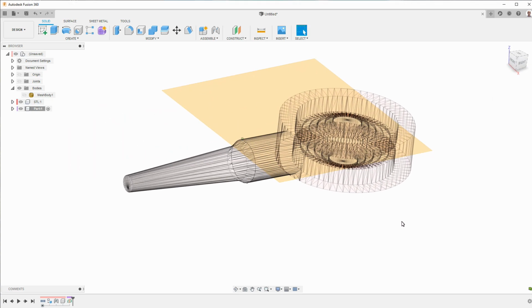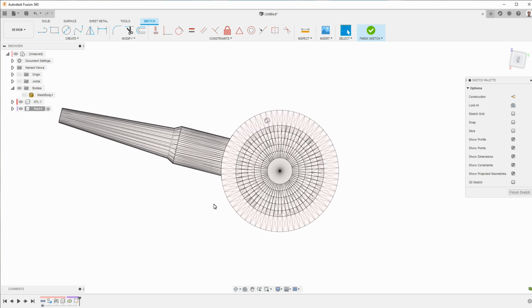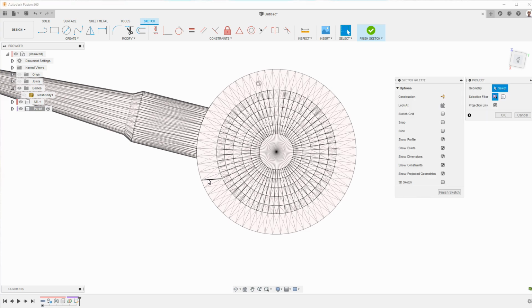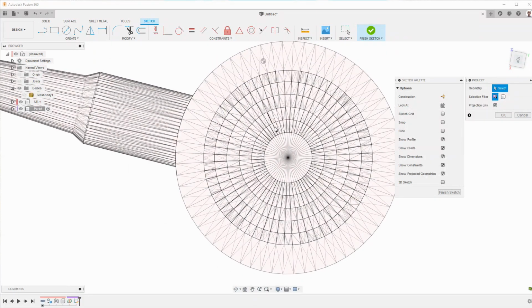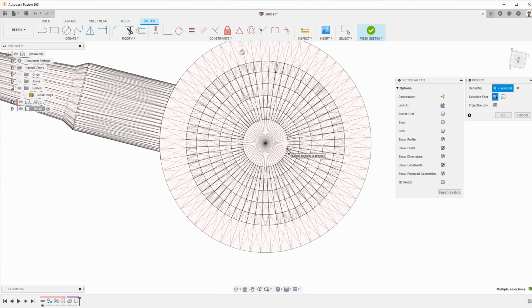So now that means that my drawing will be aligned with the XY plane. I'll make this the drawing sketch, and now I want to create some circles that represent the circles here, tied to this part. So I'm going to project basically three points for each circle. I'll start on this side and select a bunch of points. And then I'll go about a third of the way around the circle.